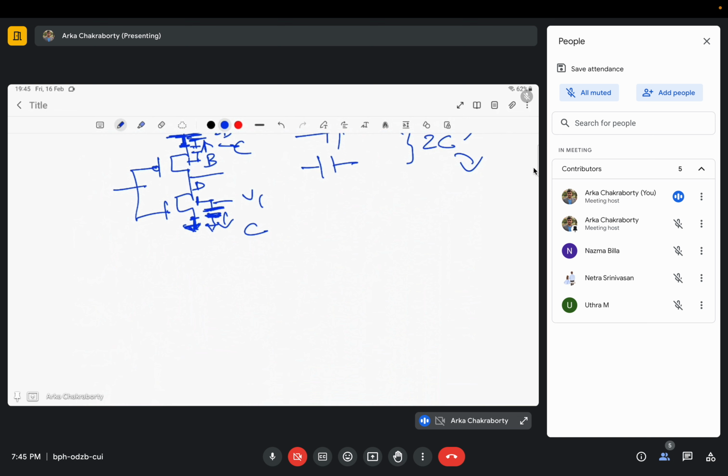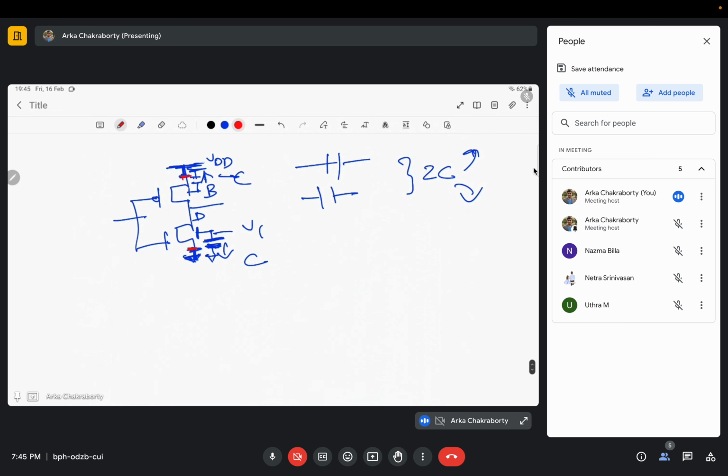Now in an inverter, the source capacitances would not come into the picture, as I already mentioned, because they are already connected to the rail to rail swing, VDD and ground. So the only capacitances left are your body capacitances. That's why I think sir introduced you to this term and clumped them together.